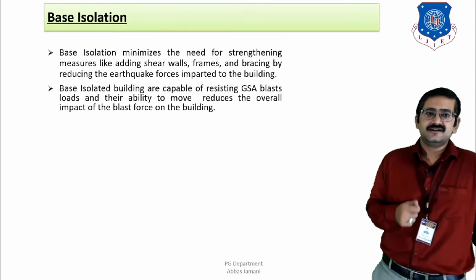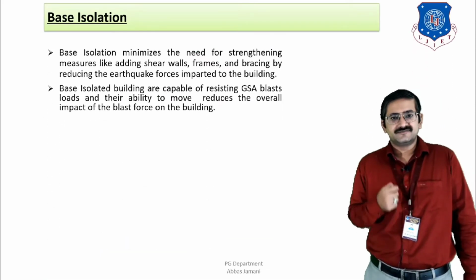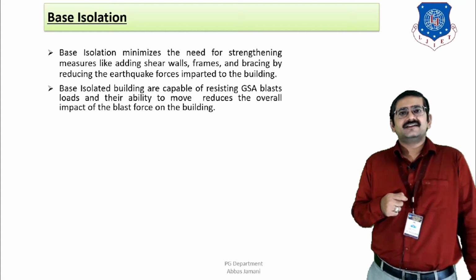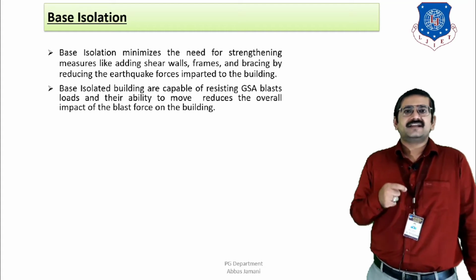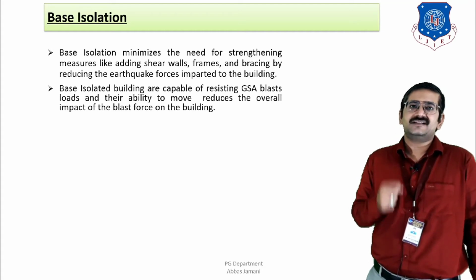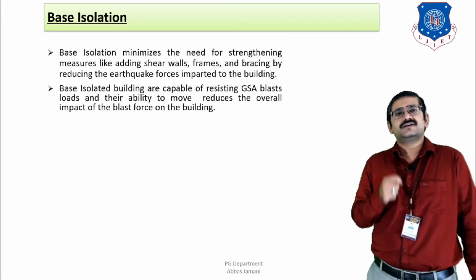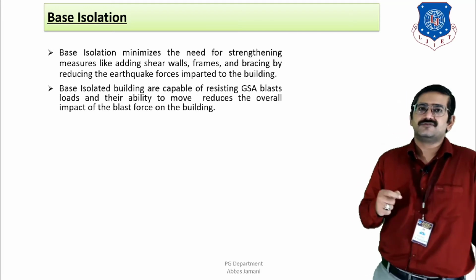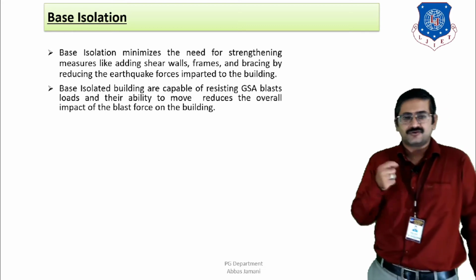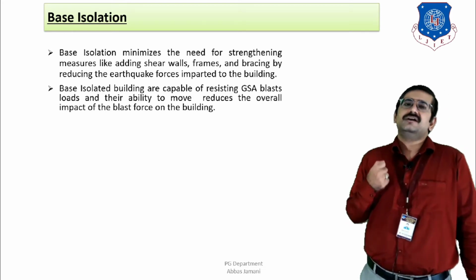And lastly, the two further advantages will be such that it will result in the dissipating of energy, and when the dissipating of energy is there, then as a result of that, the strengthening of the structure, or the strengthening of the structural frames by providing shear walls and other means, moment resisting frames, columns, can be reduced to a great extent.